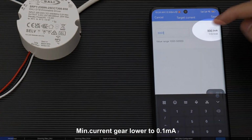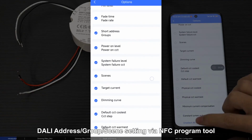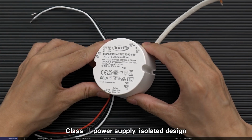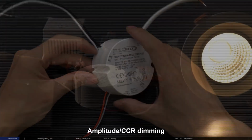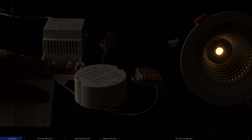Min. current gear lower to 0.1 mA. DALI address, group, and scene setting via NFC program tool. Class 2 power supply, isolated design. Amplitude CCR dimming, smooth and deep dimming, flicker free.